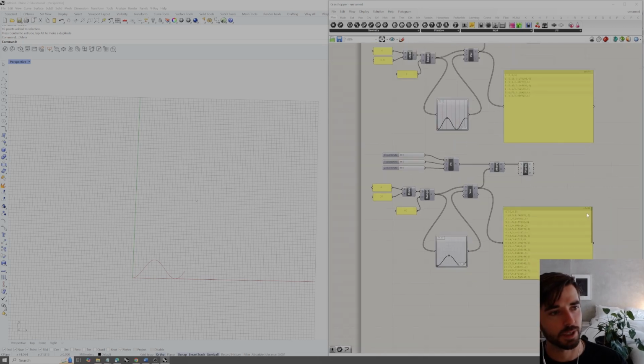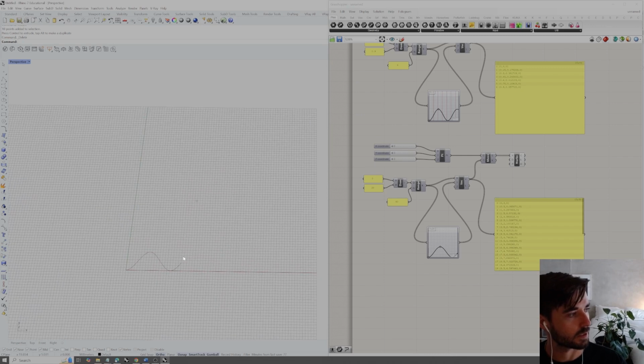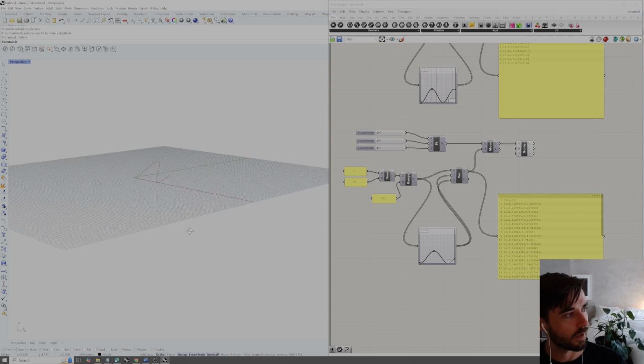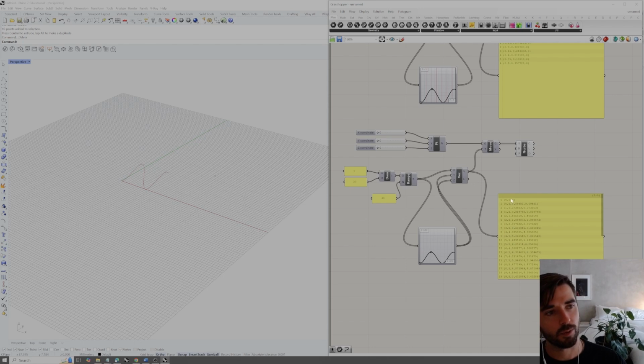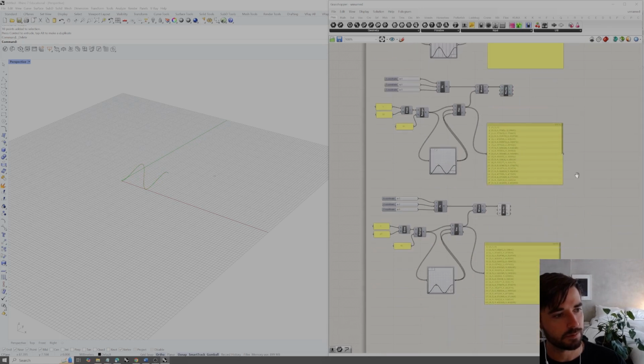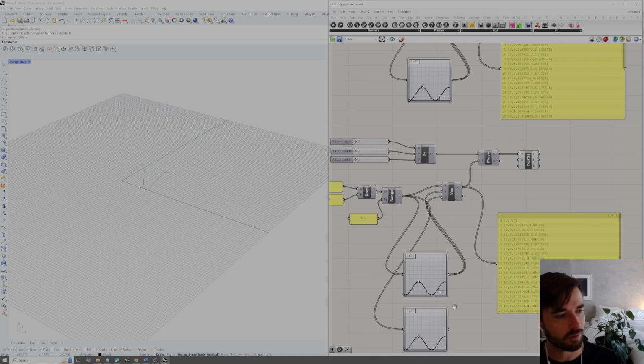Additionally, if we wanted to do this in not just this one axis or in 2D, because we can see it's not actually adjusting in 3D at all, we could plug this also into the Z. Now it's adjusting on that diagonal, and as we move it, it's adjusting in both axes. Well, if we wanted to adjust them separately, we can just copy all of these components down, hide the preview, copy this sinusoidal graph mapper, and then just plug in a different one to our Z component.